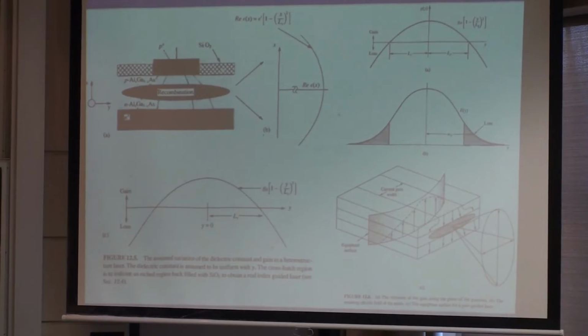The second thing is that this gain region, which is very interesting, also guides the electromagnetic wave. The light will go in regions where there is gain and will not go in regions where there is no gain. In other words, if light escapes into regions where there's no gain, it will not come back. It will not be regenerated. It will be lost forever. So this mechanism is called gain guiding. Essentially, you can guide the light with regions which have gain.